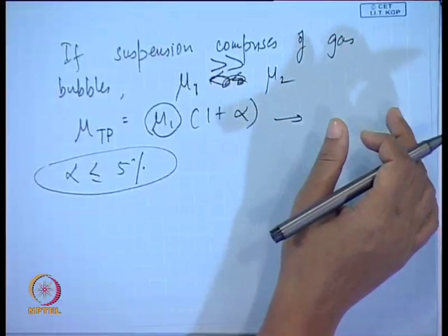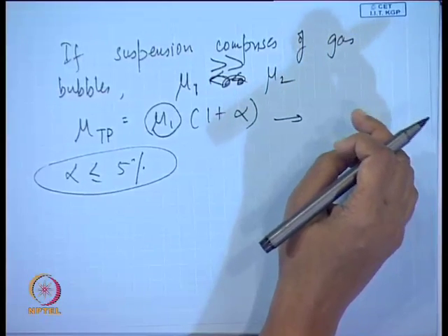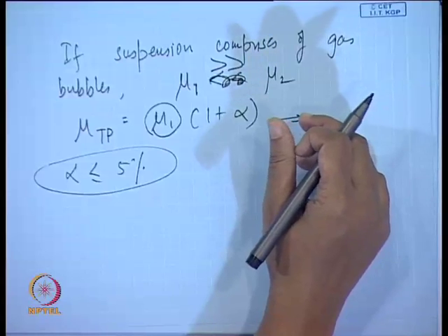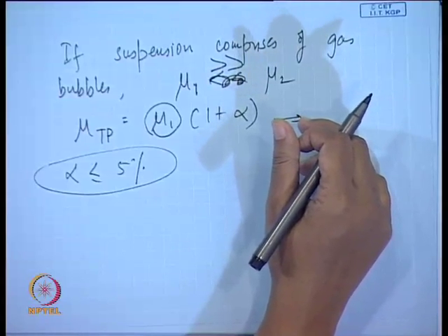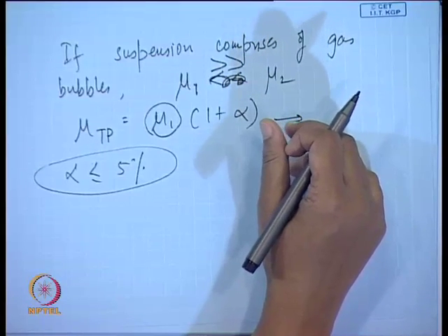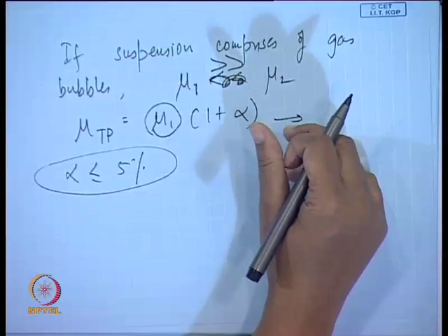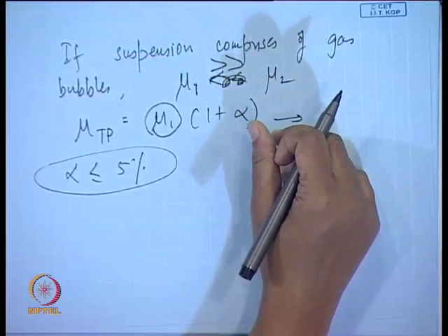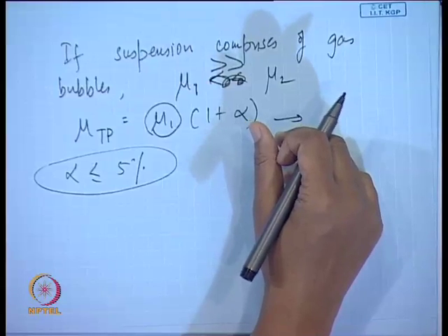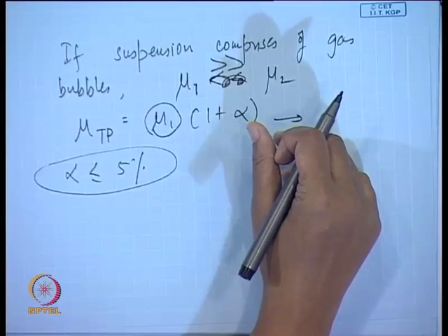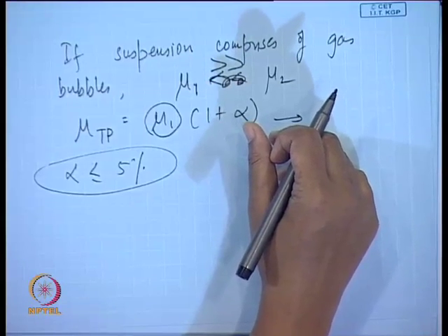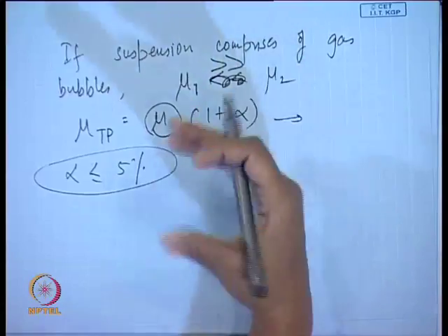Now, under normal circumstances what to do? Analytical expressions are not available. Several numerous rheological models are applicable to account for larger values of alpha and particles of different sizes, shapes, etc. It can happen the particles are of different sizes and shape, the alpha is of a much larger concentration.